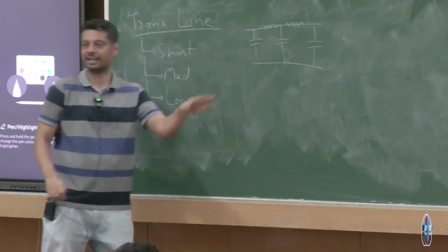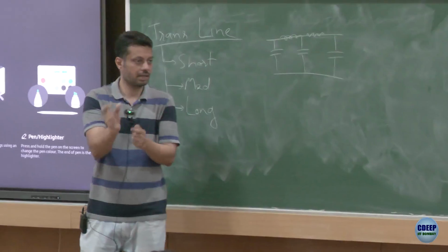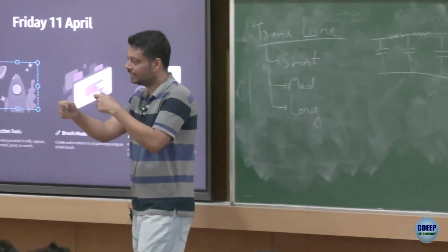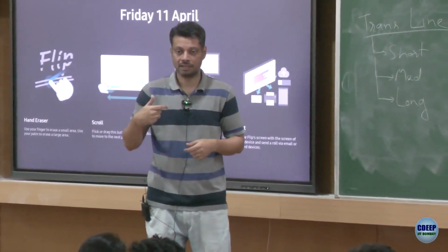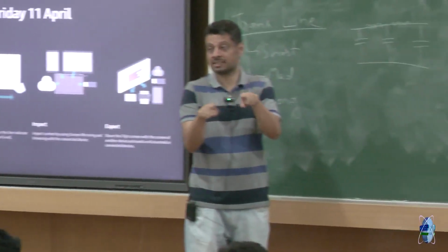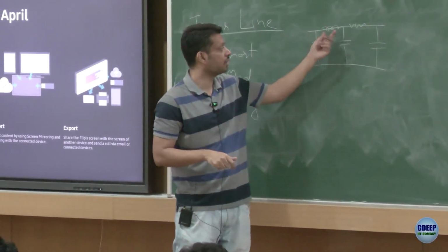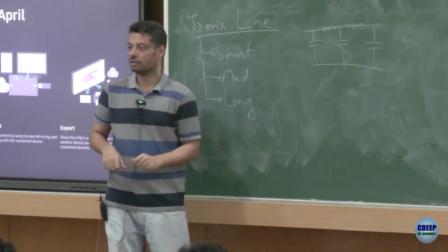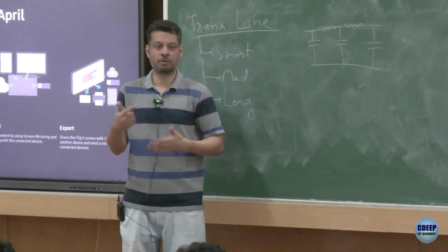An overhead line has a series resistance because of the cable conductor. It has series inductance because of the loop between the plus and the minus. And because there are two conductors, whatever the distance, there is some capacitance between them. So usually you have shunt capacitors, and series R and L. Any line which you take will have these things, though values will of course change.